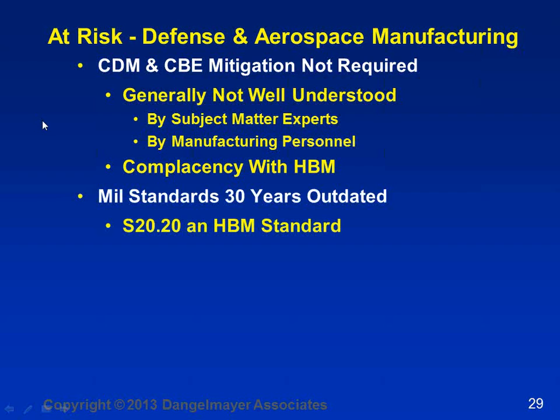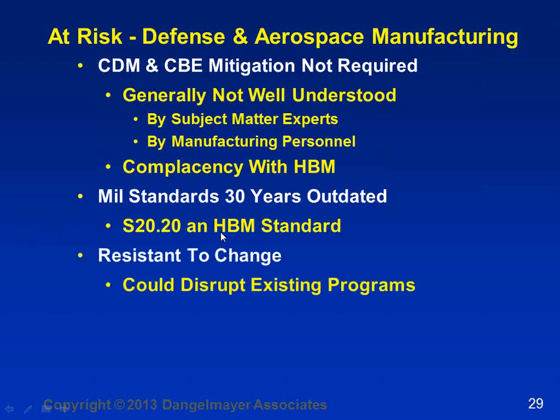As I said, military standards are 30 years outdated. 2020 is much better. It's probably only 10 years outdated, but it's definitely a good place to go. And by the way, I want to emphasize that the procedures in 2020, the HBM procedures, are absolutely essential, critically important for CDM and charged board event. If you have not done the countermeasures in 2020, you don't have a chance of doing CDM or charged board event countermeasures. So by all means, continue with 2020. You just need to expand the scope of what you're doing.